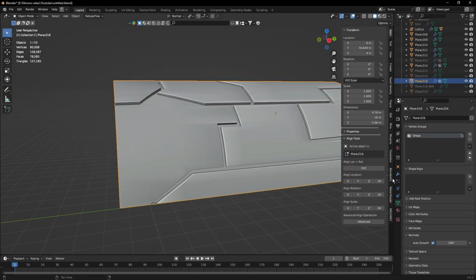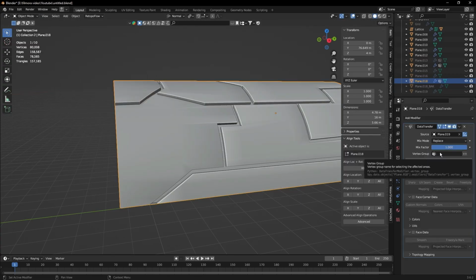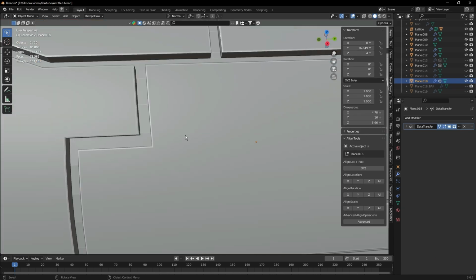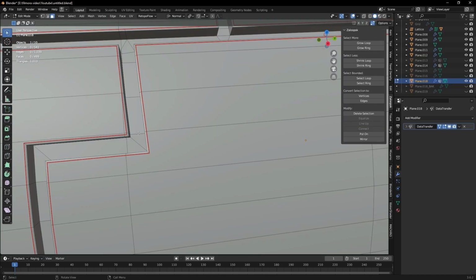Vertex groups refresher. Make a selection, plus, to create a group. Rename, assign with weight equals 1.0 for full influence. Use weights less than 1.0 to feather effects for blending.